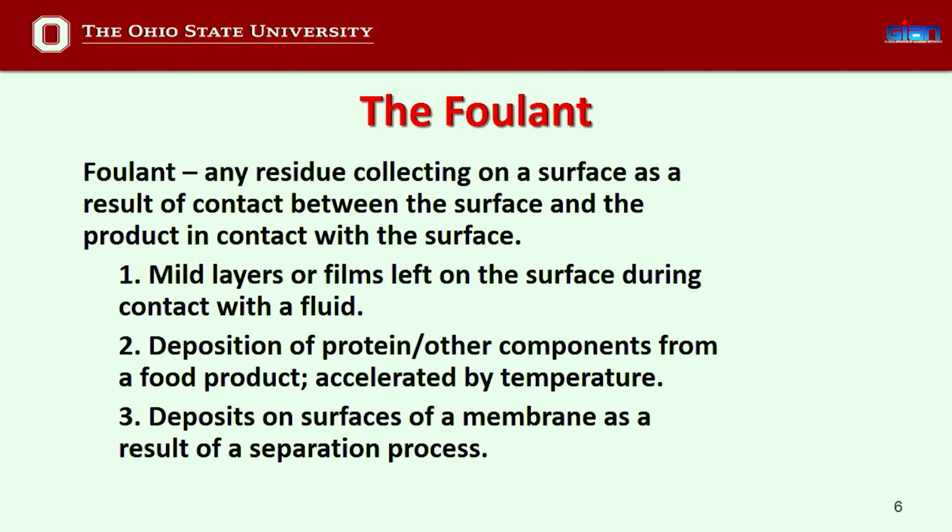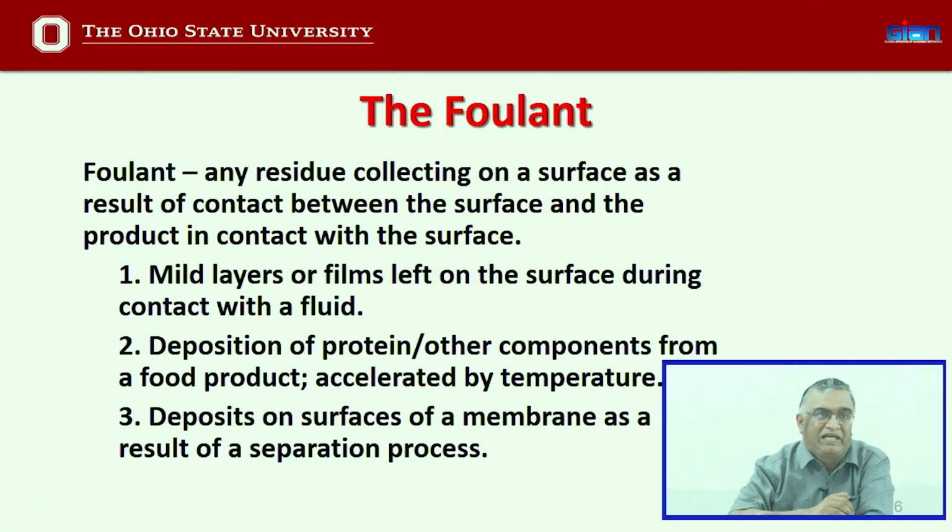The other thing, when you deal with the process equipment, we talked about this foulant. So, for example, when you are pasteurizing milk, you probably have some protein films deposited. This is a residue collecting on the surface as a result of contact between the surface and the product.